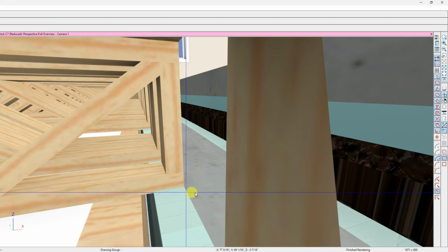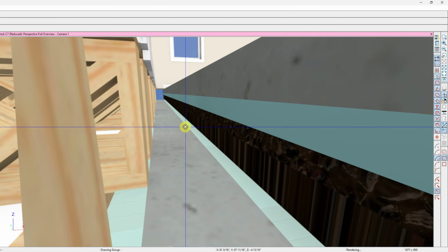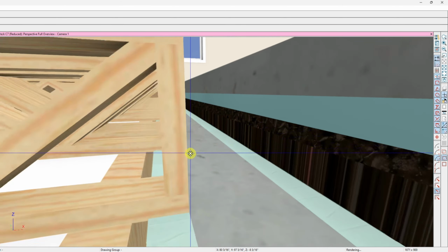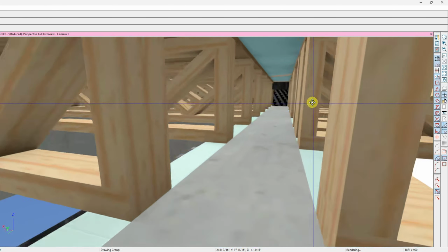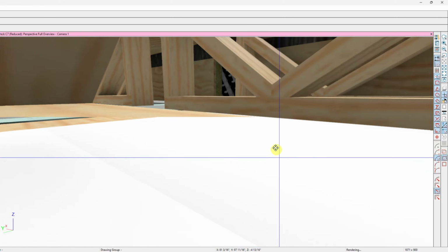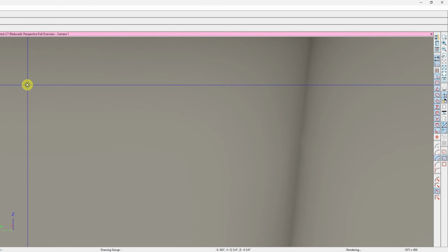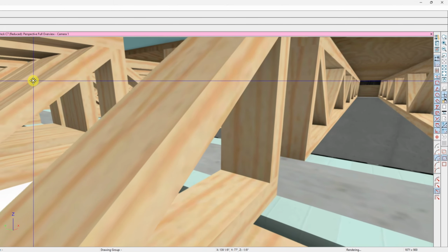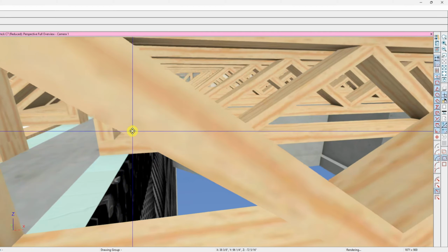It doesn't need to come necessarily over the wall, but if this wall height is all the way up, it doesn't work with the new Dura ICF block, because it should be consistent height all the way around the structure. And this framing, the floor framing, sits on the wall furred framing in the basement. So that's the purpose of why this one had to manually be brought down.